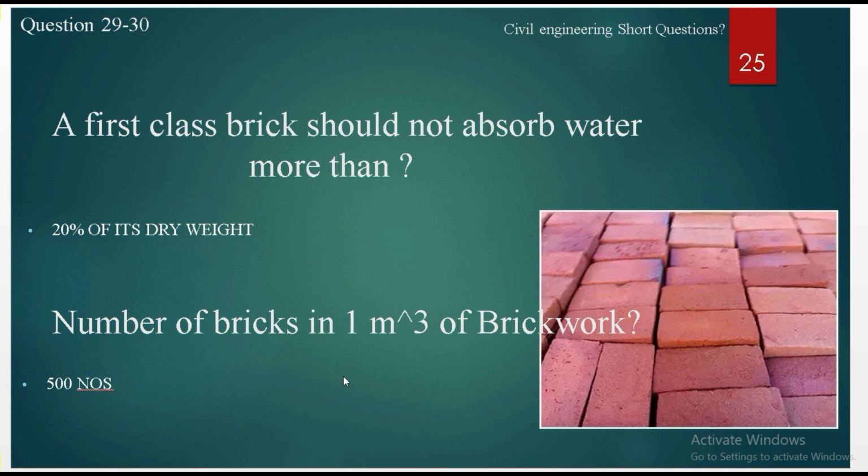And the number of bricks in 1 meter cube of brickwork is 500. This is without the mortar thickness added. If you add the mortar thickness, then it's going to be less, about 475 or something close.